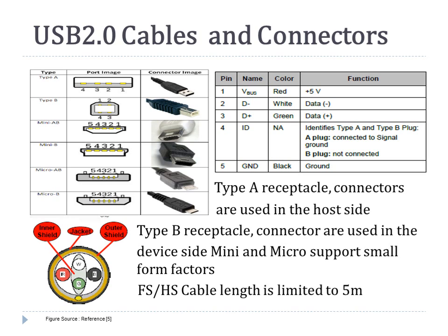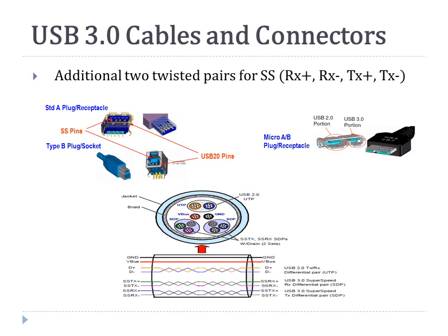The USB cable is limited to 5 meters for a full speed and high speed configuration. USB 3.0 actually is full duplex, so it has separate lines for transmit and separate lines for receive: RX plus and RX minus, and transmit TX plus and TX minus.